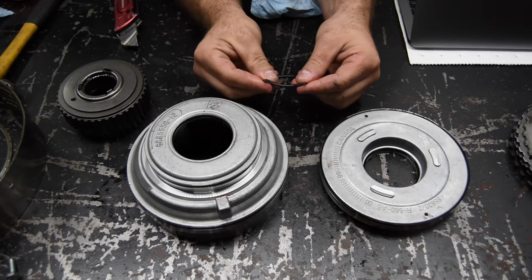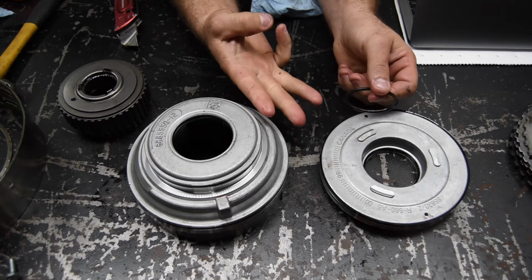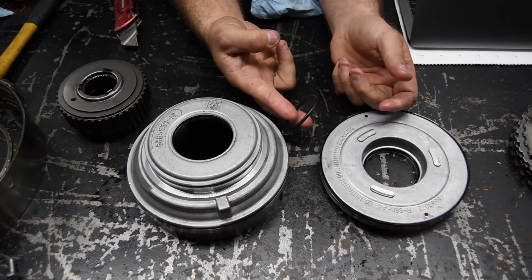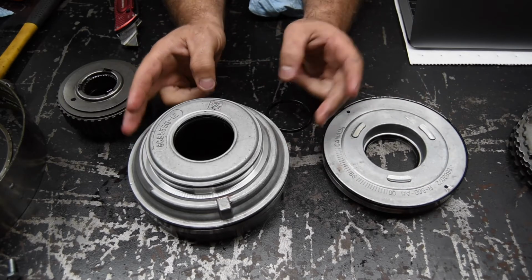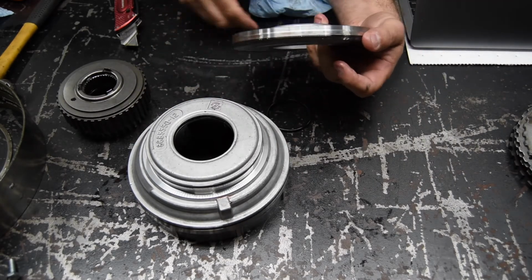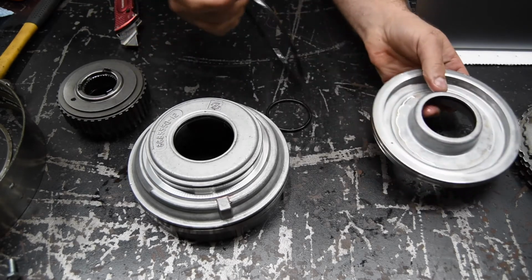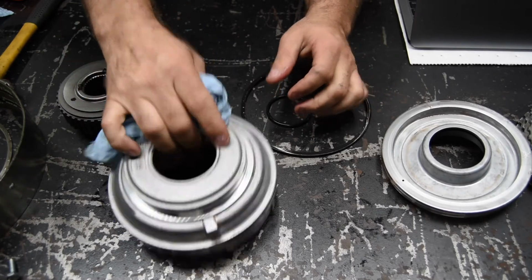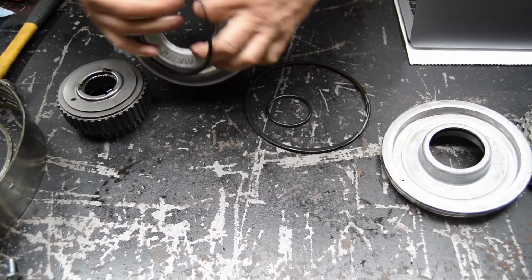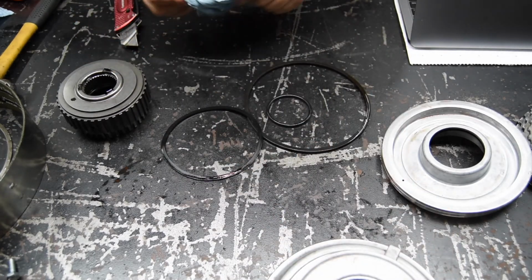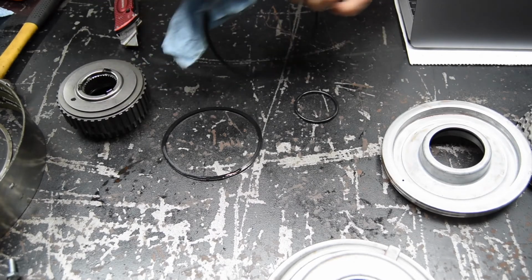It's actually in the last clutch, but we'll see that when we do it. But we have 3 different types of seals here. I've got an O-ring seal here. We have the lip seal, and then we have a square cut seal. What I'm going to do to make it more obvious, hopefully, is get a much closer shot on these things. I'm going to take these seals, or one of each, and section it so that we can actually get to see the actual shape of it.